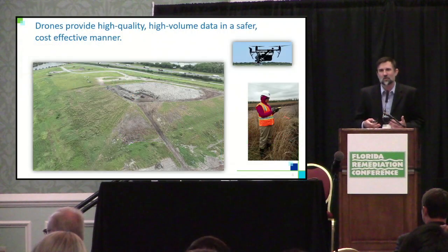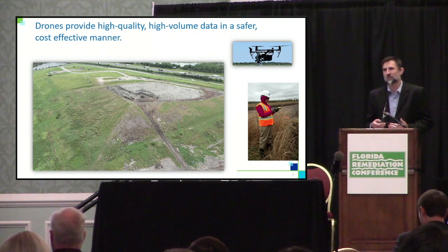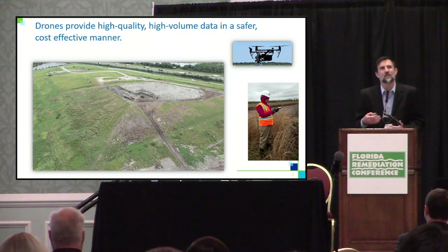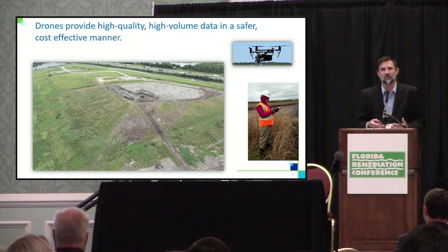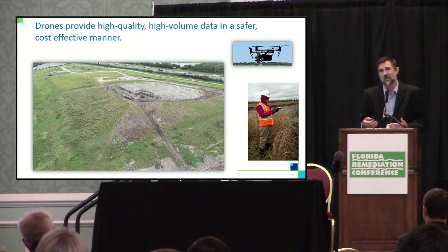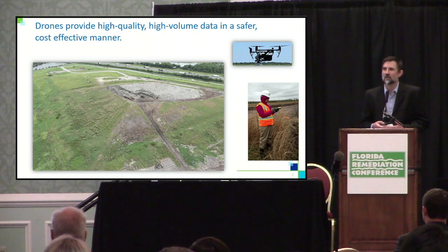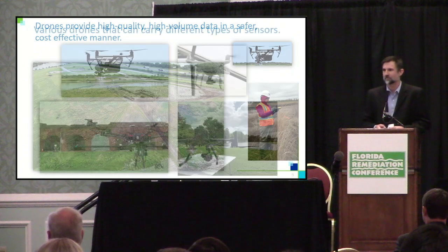So at the base, drones provide really high quality but also high volume data, and they do it in a safe manner. And so this is really important, obviously, in remediation projects where there might be heavy equipment going on or excavations, and collecting traditional field data during a remediation might be dangerous to people. Or the contaminants of concern might be radiological or have other human health concerns, and we don't want people spending that much time in there. So drones can help us out and collect a lot of data safely without having that human exposure pathway.